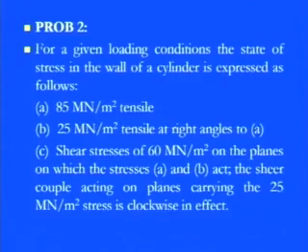As far as the sign convention is concerned, if it is a tensile stress component, you need to take the sign convention as positive. And also for the shear stress, if the object tends to move in a clockwise direction because of the shear stress, always take it as positive.